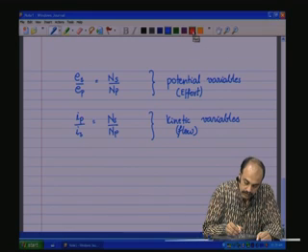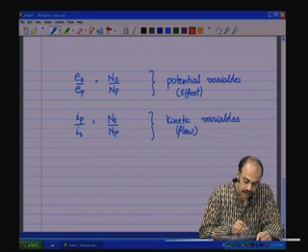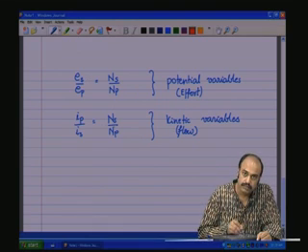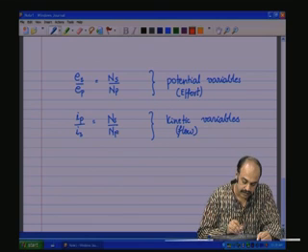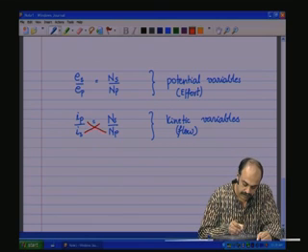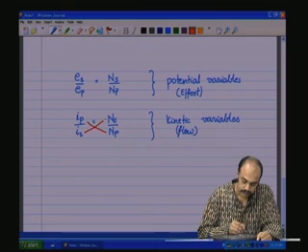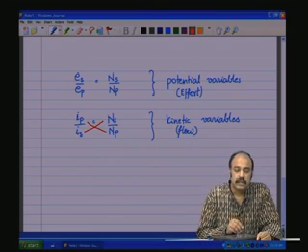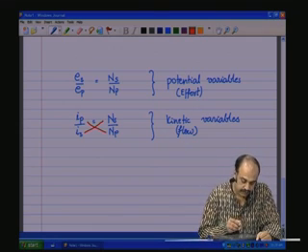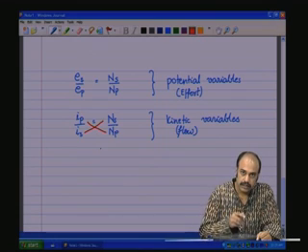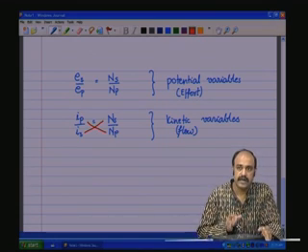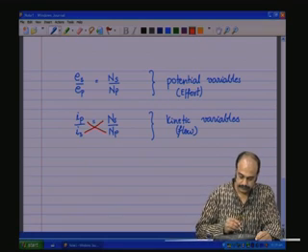Note here the inverse proportionality, Es by Ep, which is equal to Ns by Np. Es is proportional to the number of turns. The current is inversely proportional to the turns, Ip and Np, Is and Ns, so that the energy conservation is obeyed, so that the power at the primary and the power at the secondary under ideal conditions will be the same.